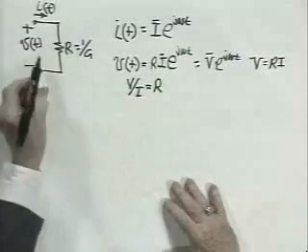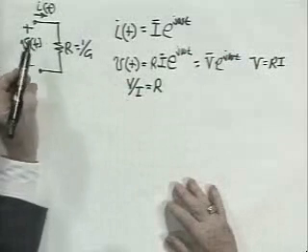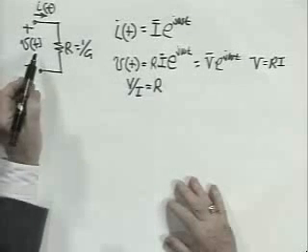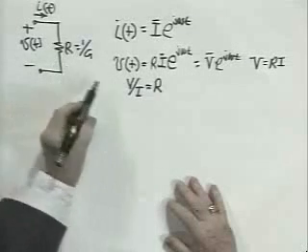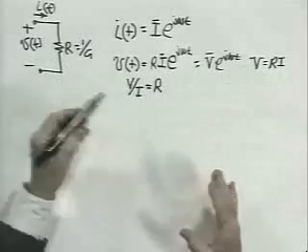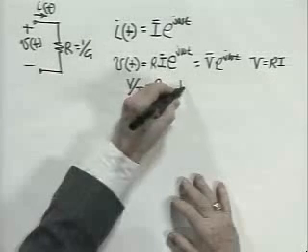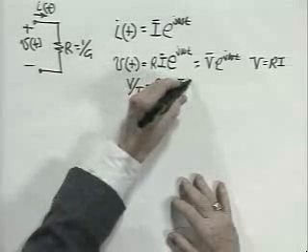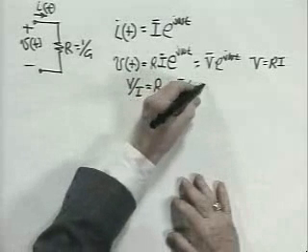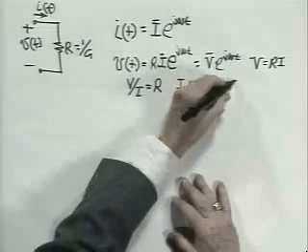So if I excite a resistor with a complex exponential, or equivalently a sinusoidal time function, I get a complex exponential or sinusoidal time function for the voltage, and the coefficient I multiply the current by to get the voltage is just the resistance. Or if I turn it upside down, drive it instead with a voltage, and want to calculate the current, I can calculate I over V, and that's equal to 1 over R equals the conductance G.